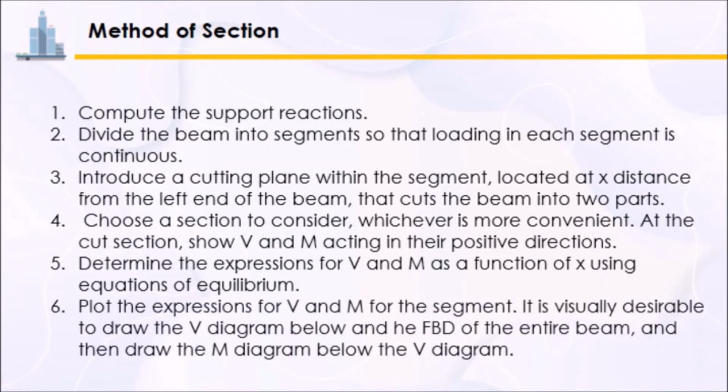And then lastly, since may equations na tayo, we can now plot the expression for shear and moment for the segment. It is visually desirable to draw the shear diagram below the free body diagram of the entire beam, and then draw the moment diagram below the shear diagram.